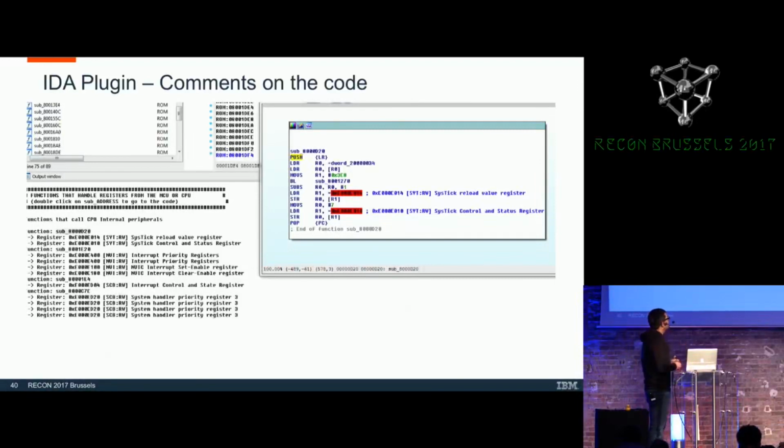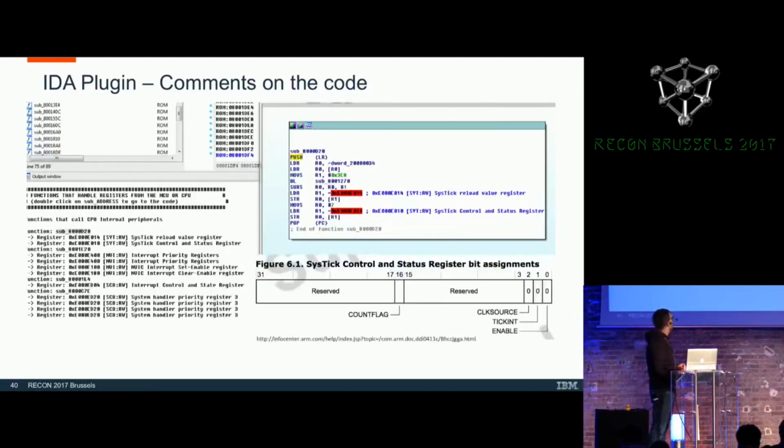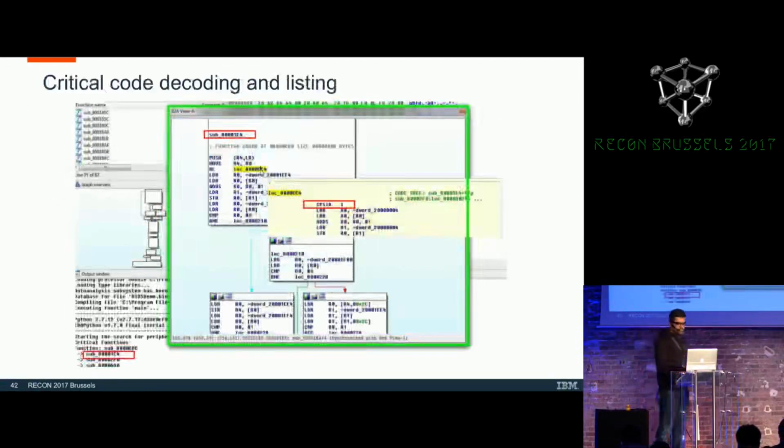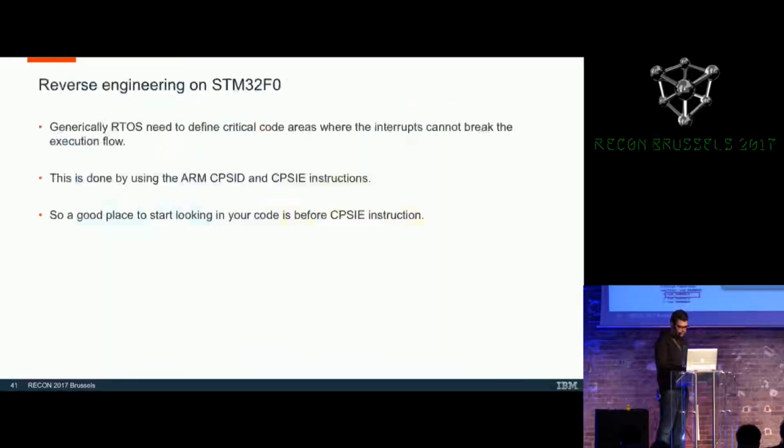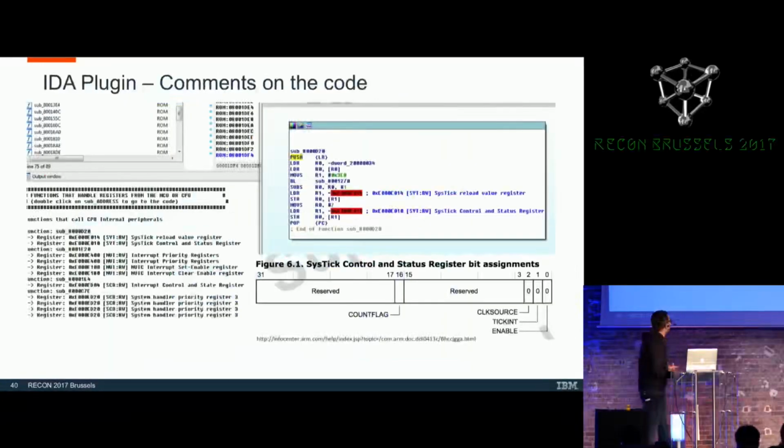What we are seeing here is that we are configuring the register for the SysTick. So the first one, we are giving it 1,000 ticks, and after 1,000 ticks, it will do something, and that's defined by the second register, the SysTick control register. So if you look at the documentation, we should be going through the next slide. Oh, sorry, my PowerPoint crashed. Okay, yeah, so we're here.